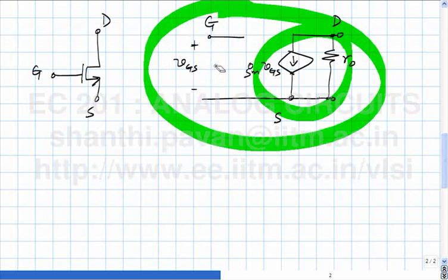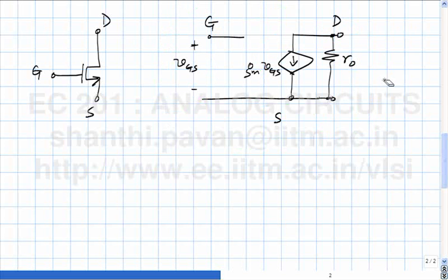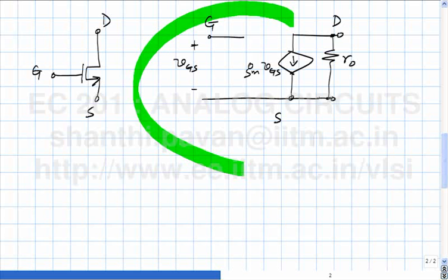In practice, as we would logically expect, there is always finite speed, and when there is inertia of charges moving about, it turns out that you have to actually get into the nonlinear operation of the device, write the nonlinear differential equations, apply a small signal change, and then do what we did before. How did we derive this equivalent circuit?